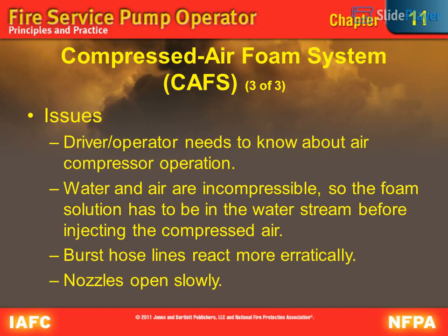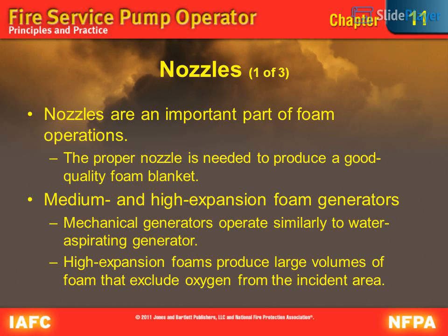Compressed air foam system, CAFS, 3 of 3. Use. Driver/operator needs to know about air compressor operation. Water and air are incompressible, so the foam solution has to be in the water stream before injecting the compressed air. Burst hose lines react more erratically. Nozzles open slowly.